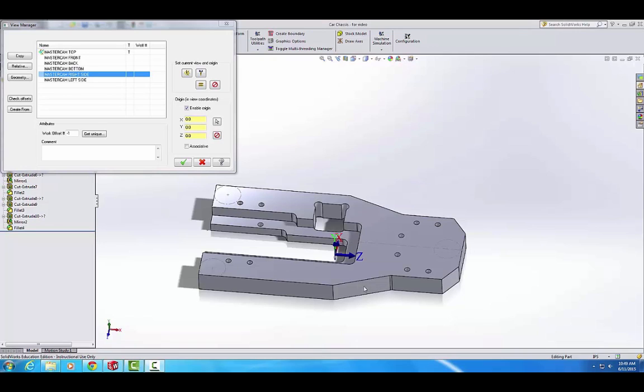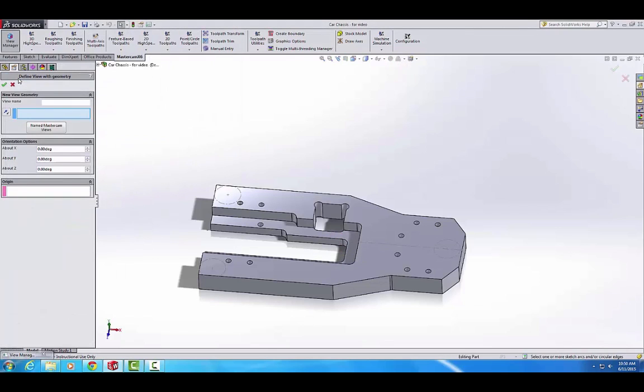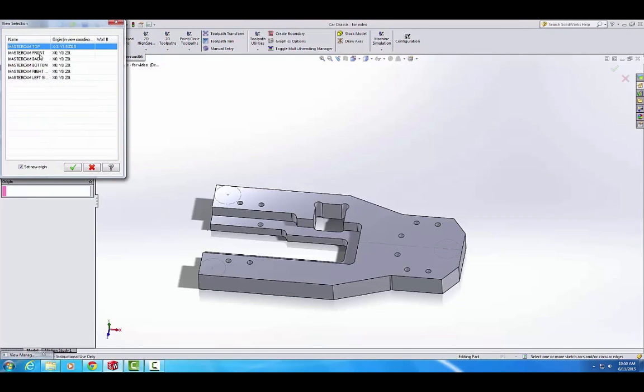In our case, editing the origin to place it in the upper left-hand corner is relatively easy, but in other cases it is a bit more difficult. If you are having trouble placing the origin in the correct location, you can actually create a custom view. In order to do that, you have to go to Geometry, and you have to choose a view to base your custom view off of.